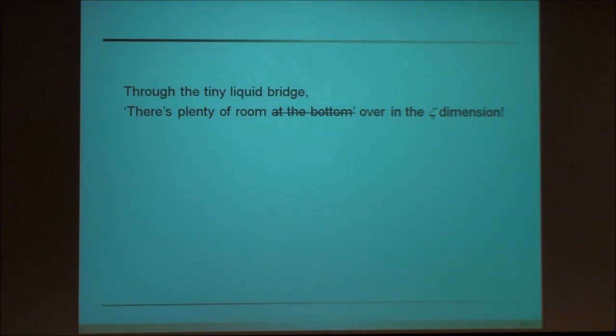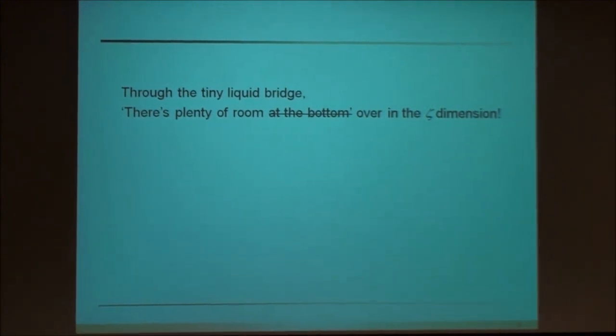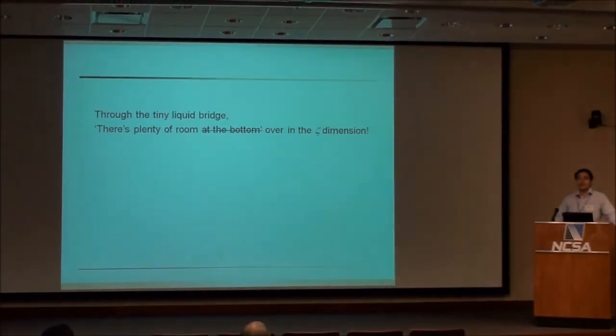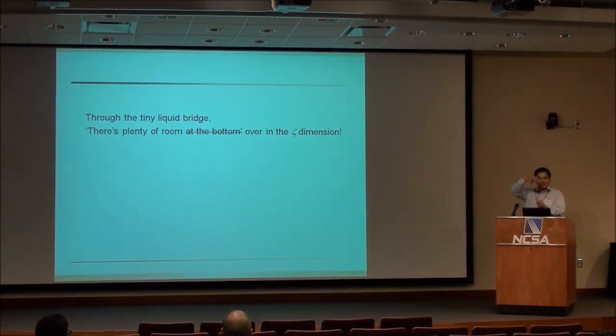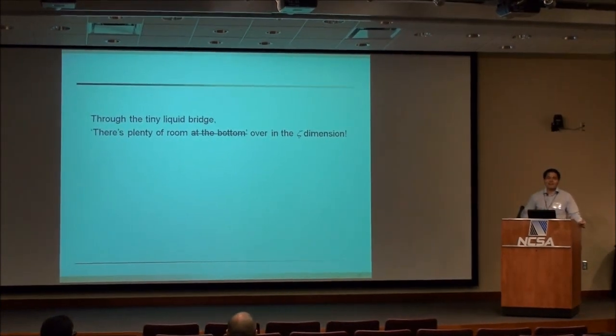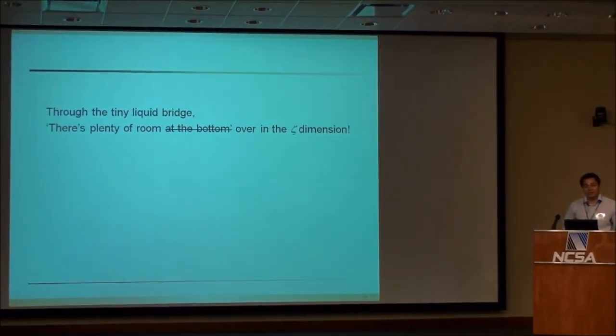Does the size of your nozzle affect your maximum growth speed? I didn't include that data here. Just like I mentioned, since we have the meniscus in between, suppose you have a 1 micron nozzle, we have adjustability from 1 micron down to 500 nanometers. Those adjustments are not made by changing the size of the nozzle, but by changing how the meniscus is stretched. So in that process, yes, the growth rate will change slightly.